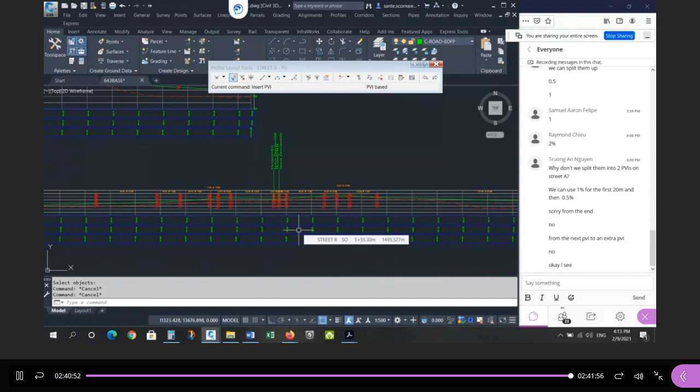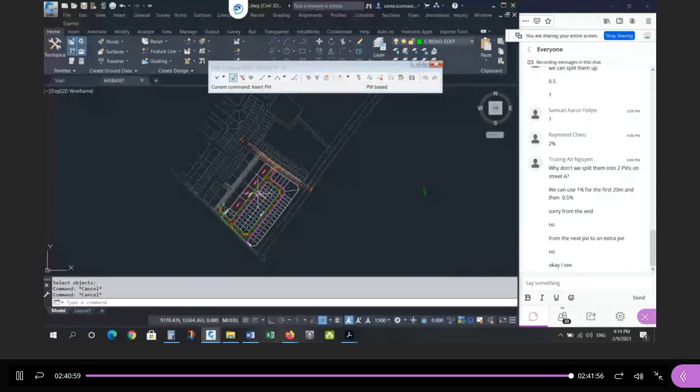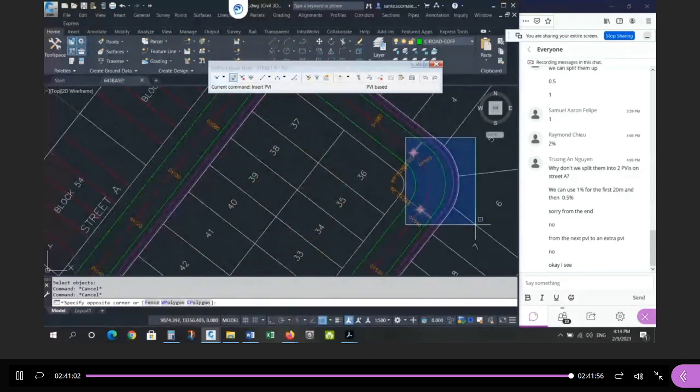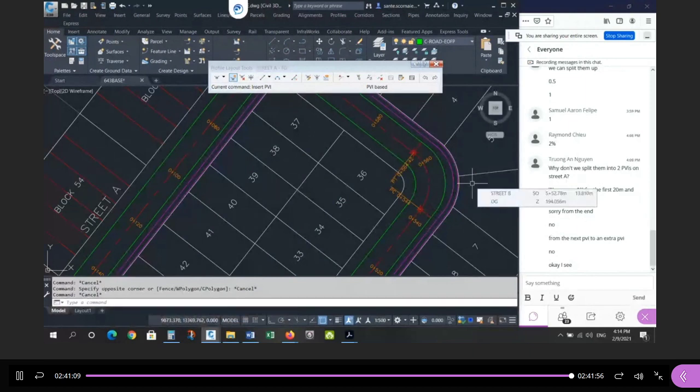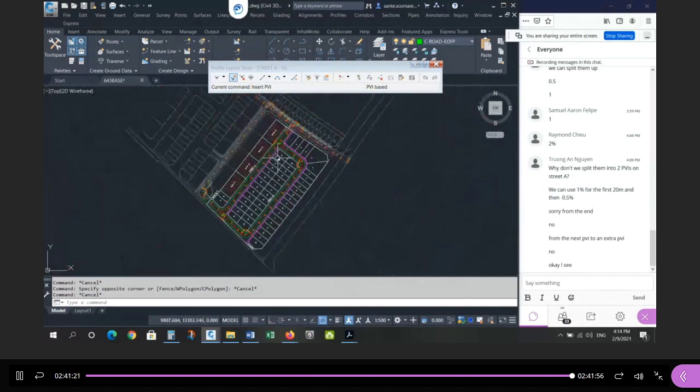Okay. If you want, you can create the corridor, add street A, add street B to the corridor model. The other thing you have to do, which I haven't covered yet, is you have to update the elbow. Remember, you need to split the region, create an alignment along the gutter line, right? So review the corridor model that you did in Richmond Hill last semester. We still have to do that. And then we'll get to the grading, okay? So that's plenty of work for next week. At the very least, see if you can get to the same point that I left off at, right? And then I'll redesign street B to match street A, and then we'll get into the elbows, all right?